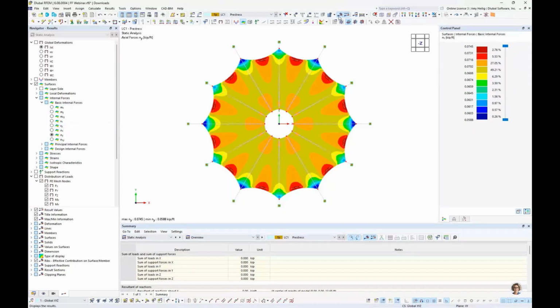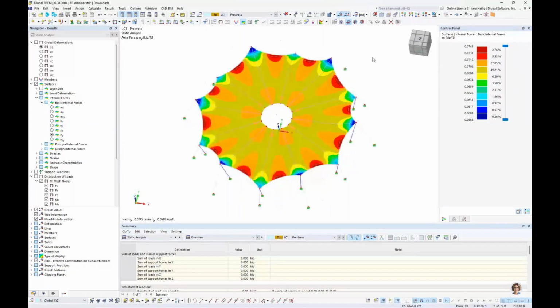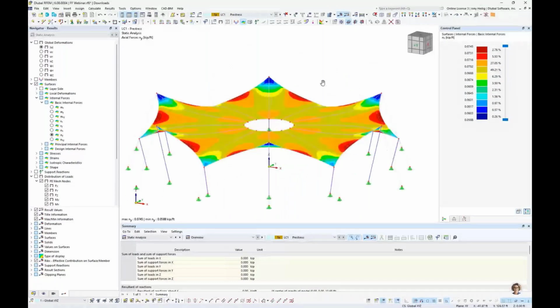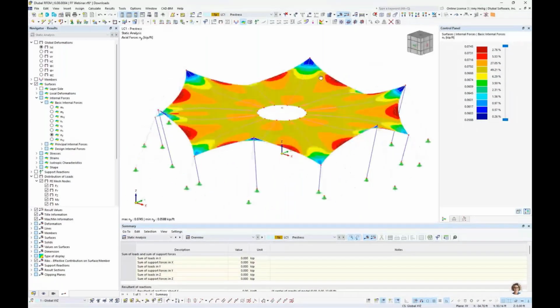Okay, so also just to mention verbally, we won't do this in our example today, but it might be quite common to place in here temporary supports during the form finding process. Perhaps we have temporary supports at the tops of our columns that will be used when we're applying these pre-stress forces out in the field. And then we remove them before we apply additional loads like live load or snow, rain, and so on.